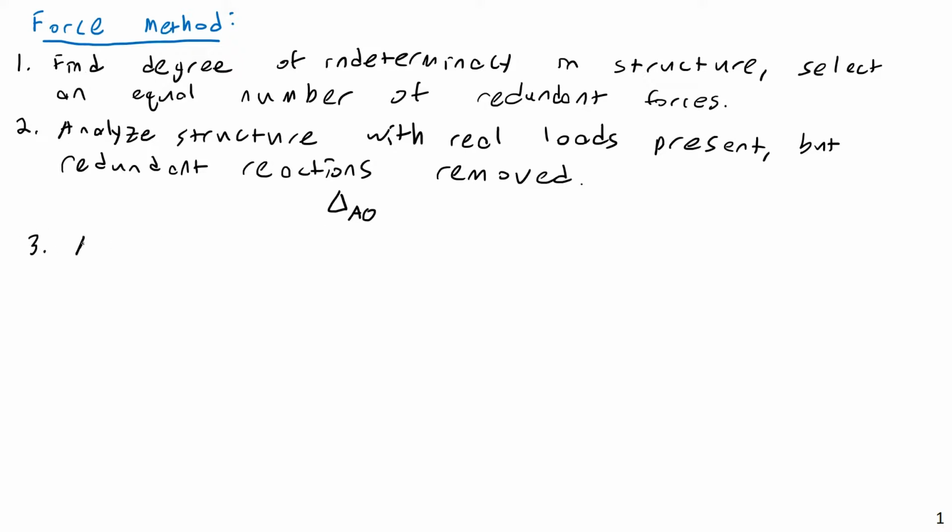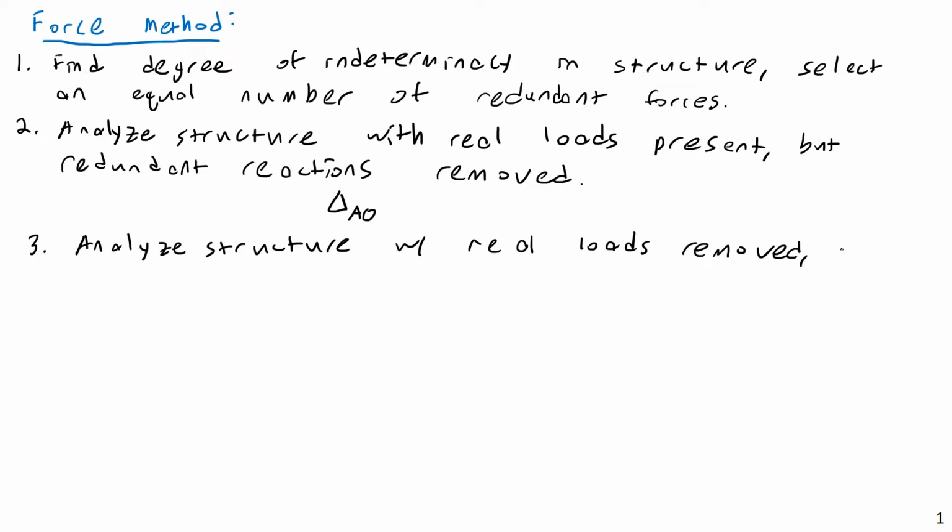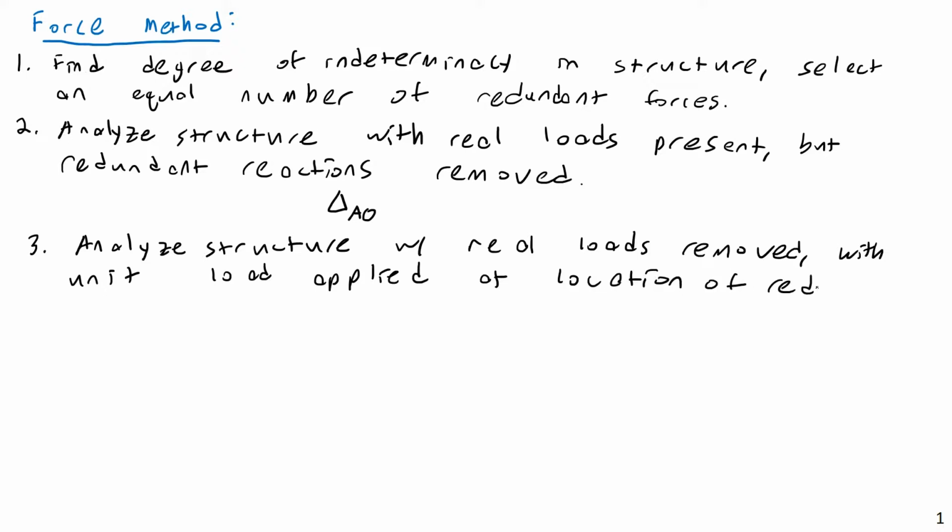Then, secondly, I will analyze the structure with real loads removed, but a unit load applied at the location of the redundant.